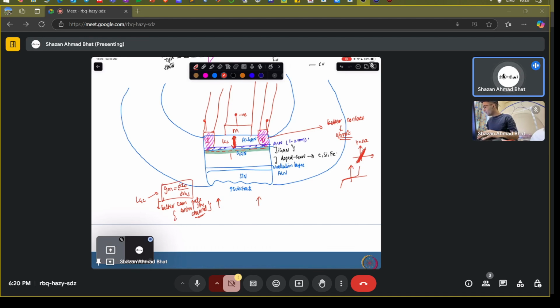You make something called a titanium contact, titanium nitride or titanium alloy, so that the titanium goes and reacts with this particular layer, and they form something called a titanium nitride species. And because of nitrogen vacancies, they have a large number of electrons. So when you have a large number of electrons there, it almost becomes an n-type contact.